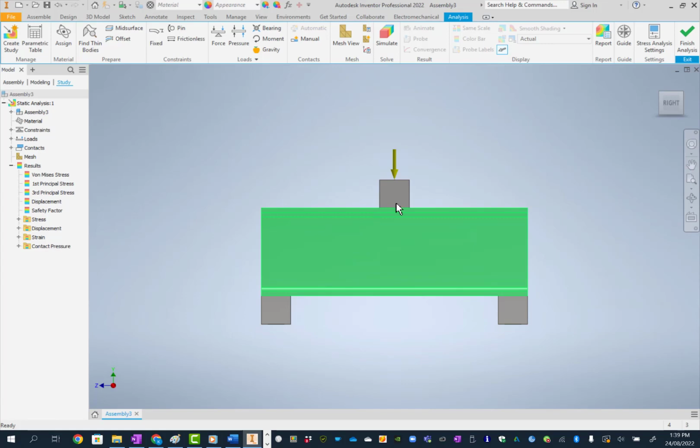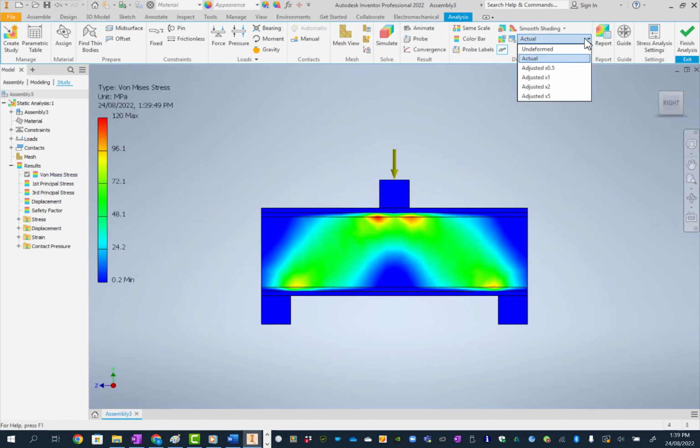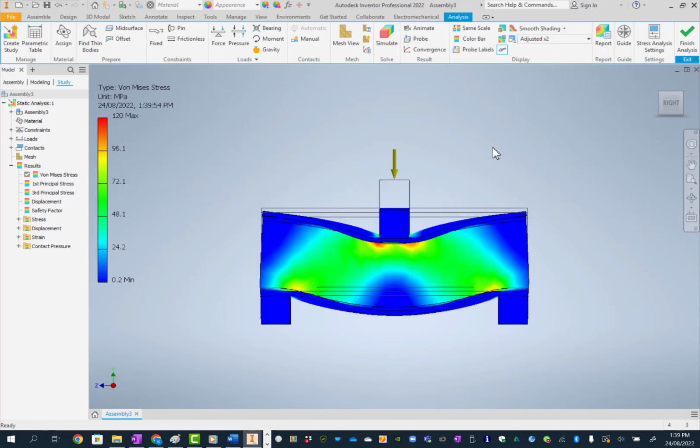And that's what I'm talking about with rigid bodies. It might look like nothing's happening. This seems like a rigid body, but actually it's deforming a little bit. What we can get this program to do is exaggerate it. It's not really times 5, but we'll just times it by 2. It's just exaggerating the deformations of the beam. It's multiplying them by a factor.